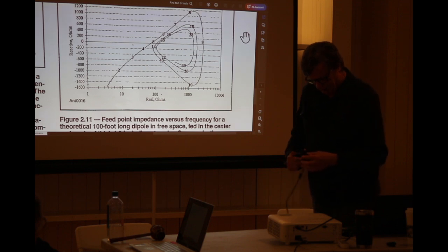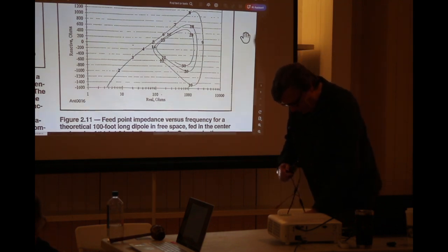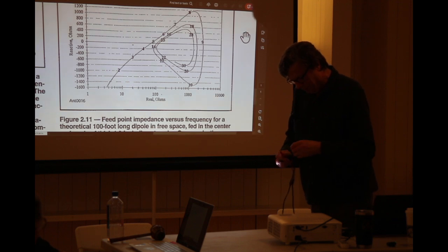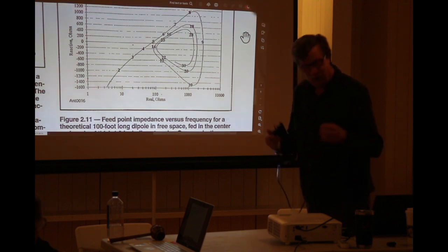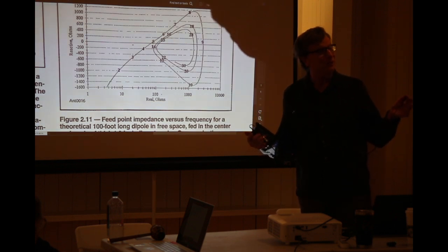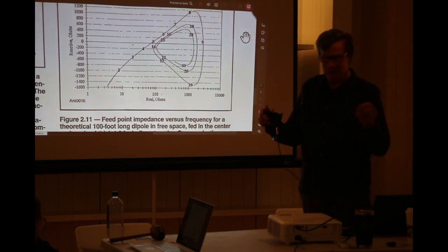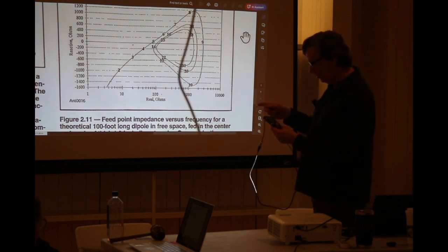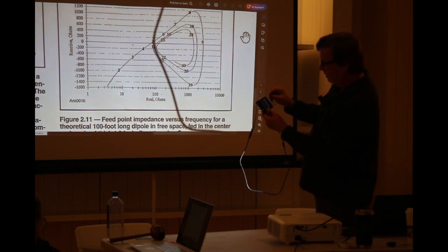And now I take my load. And the beauty of doing this at the end is it doesn't matter how long or how lousy this transmission line is or how many different impedances you have in between. If you do this calibration, it will tell you what the impedance is there, which is really, most of the time, what we want. Now I just hit load.